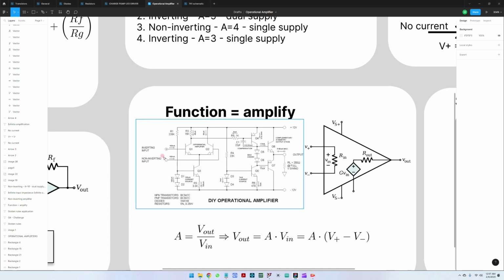Okay, so we've defined that we need an inverting input and a non-inverting input. These values are fairly at the same voltage level. We also have an output. Here the differential pair is going to the final stage where the amplification is done so that you can have a bigger output and not influence the differential pair on the input.